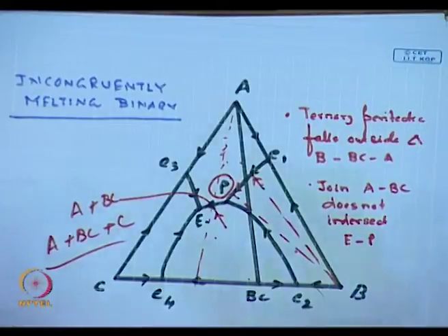You see, there can be lots of variations to these three-phase diagrams. These diagrams become very important when we are talking of liquid phase sintering. This is not so important in solid phase sintering, but the very fact that we have a range of materials like silicon nitride which are best sintered through liquid phase sintering, many of these diagrams become operational.